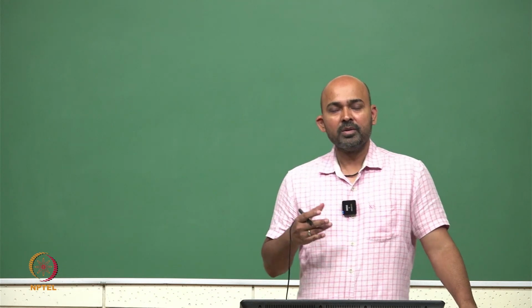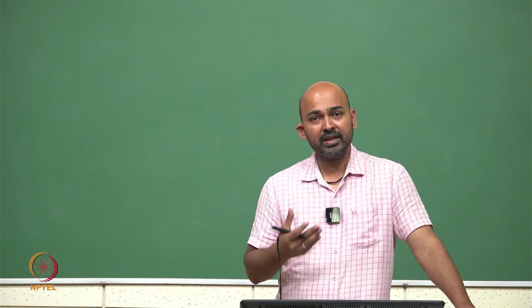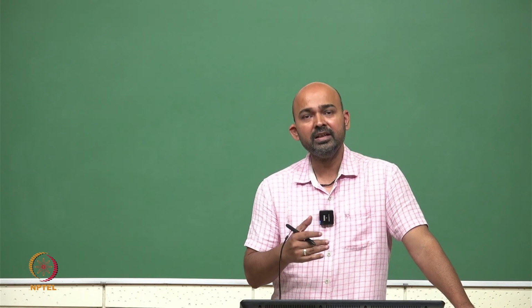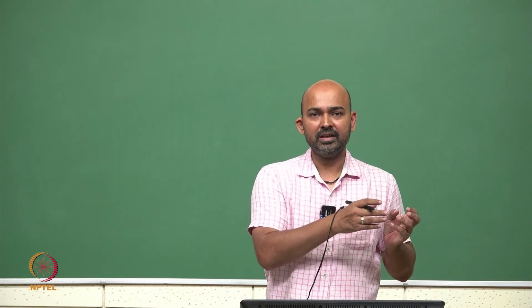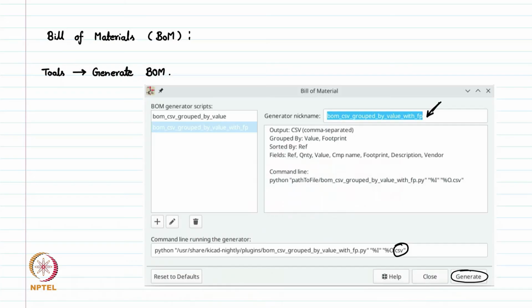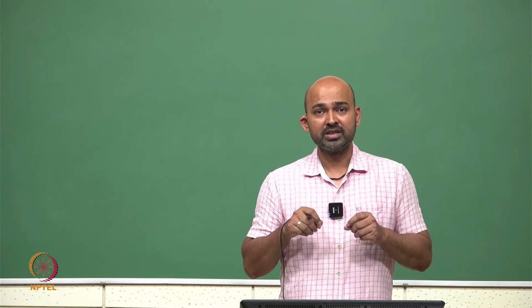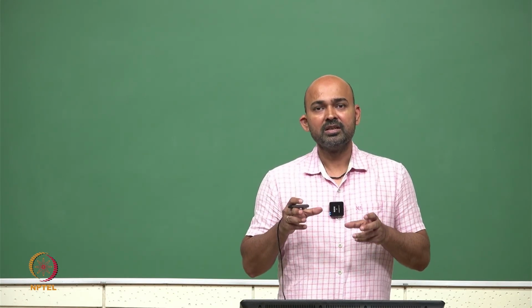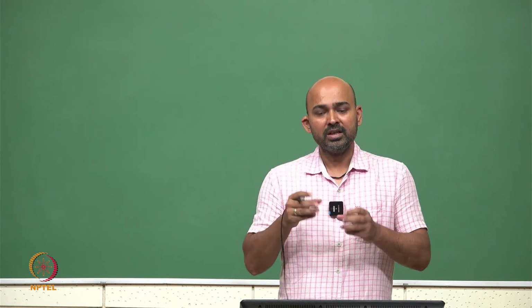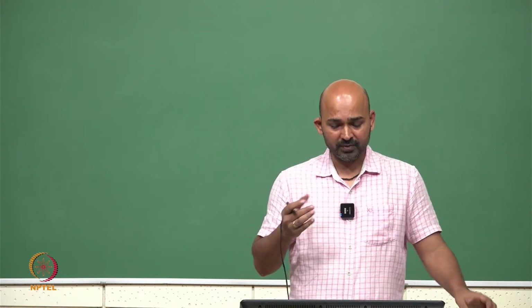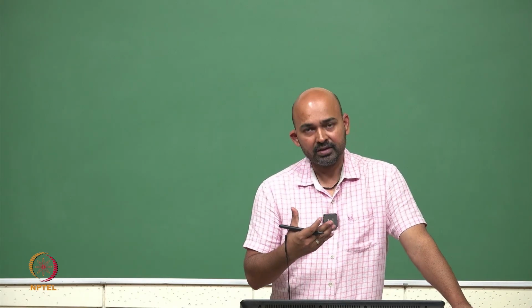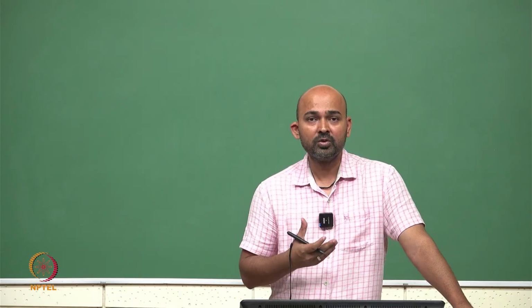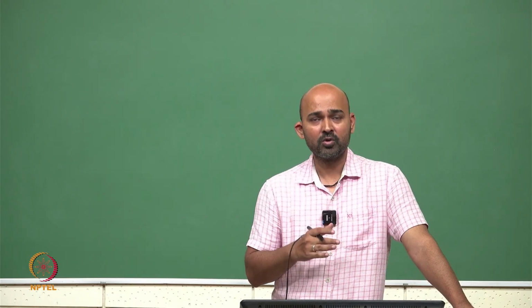So today we saw in KiCad how we systematically design a schematic. We start from the schematic editor, we take all the devices together on the window which is called the schematic sheet. The size of that sheet we can specify, we connect them together, we move or rotate the components. Then we saw we have electrical rule check where we can find out common errors.